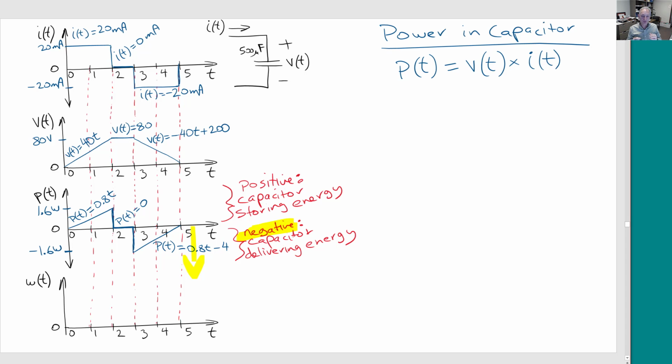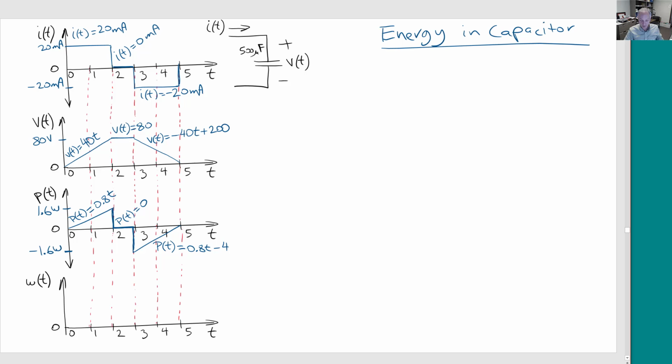So similarly, the capacitor's power is negative when it's supplying energy back into the circuit. The stored energy is being released back into the circuit. We can also see that it's losing energy by the magnitude of the voltage going down, okay? The magnitude is decreasing, okay? So it's losing energy. Okay, so that's that part.